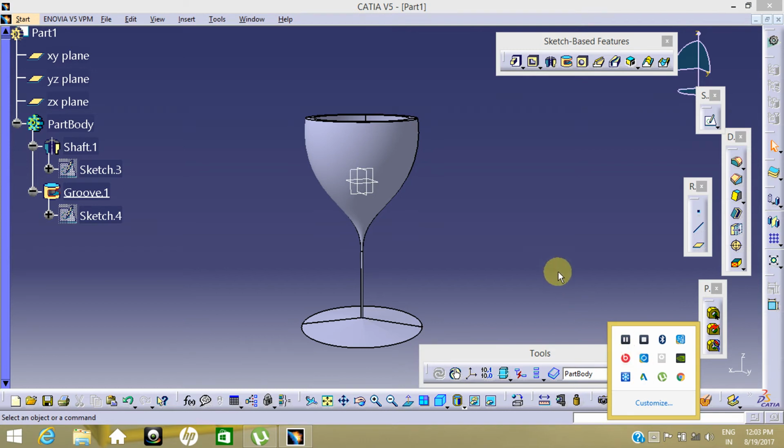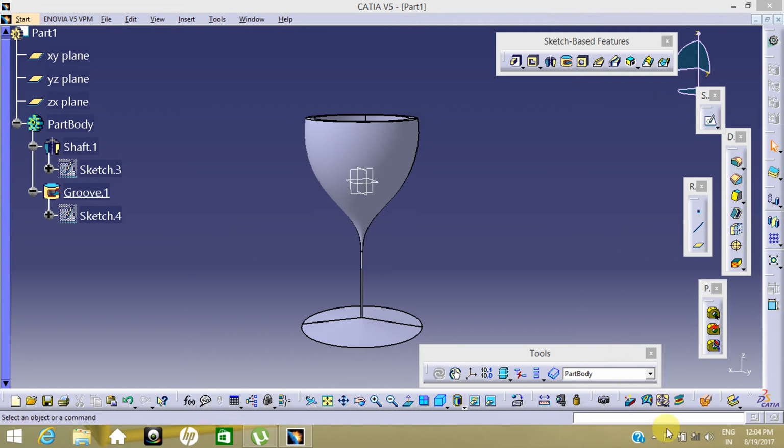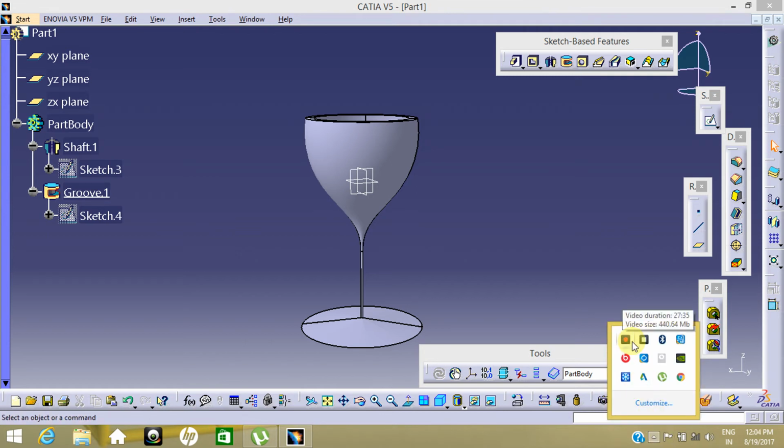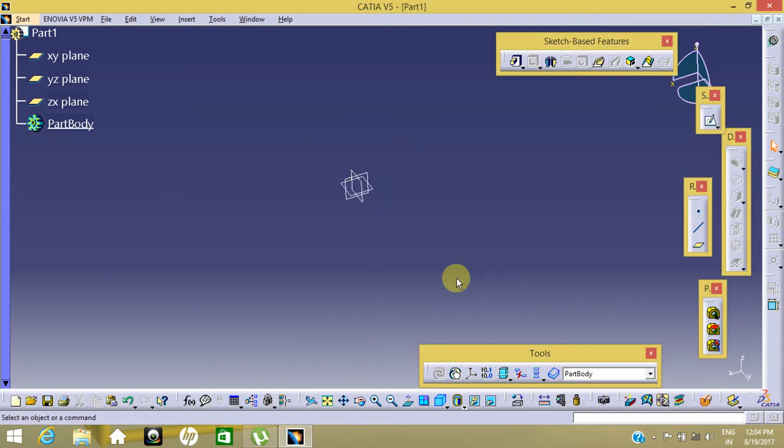So select the sketch again on the perpendicular plane here and draw a path which you really want to move. Our path might be open or closed, it doesn't matter, but it must lie in the sketch like this.